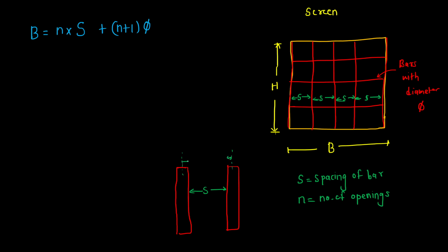You can see, this distance is half of the diameter. So for the last bars which are present here, there will be half of the diameter and half of the diameter, and the remaining ones are those present in between. So there are total 3 plus half and half, that will be 4. To reduce that calculation, you can directly write the formula which is given here.